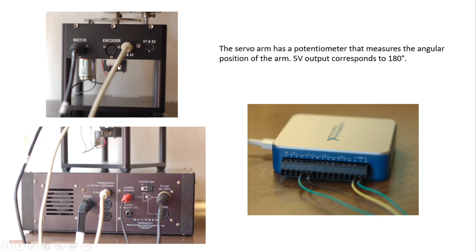This signal is going to go, this is the same wire right there, to the amplifier where it says analog sensors, and the same signal is going to go to the ADC. This has four RCA type connectors, and one of them is sending out the sensor data, and it's connected to analog input, right?